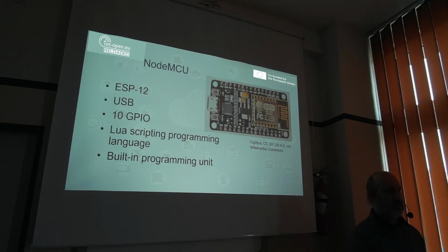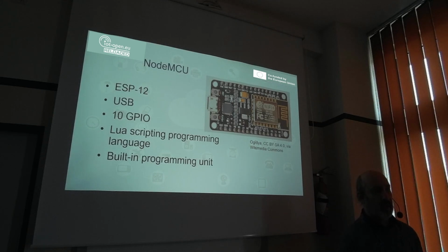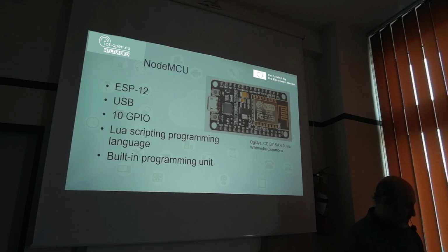It can be plugged into some socket, into some experimental board, and connected with simple wires to other elements. This exposes 10 GPIOs, and normally the software that comes with this module allows us to program it with a scripting programming language named Lua.